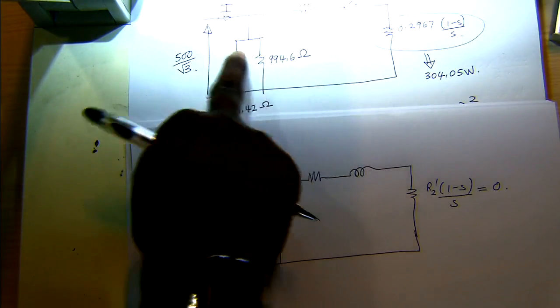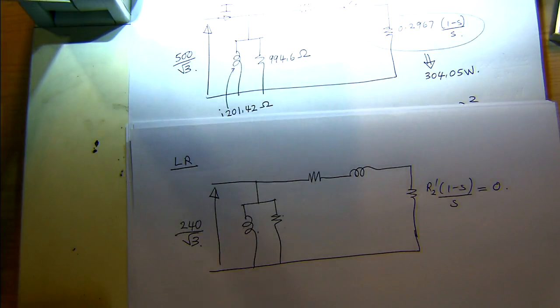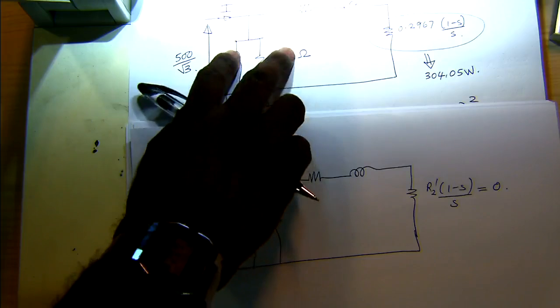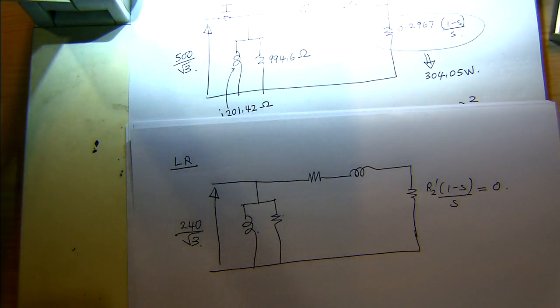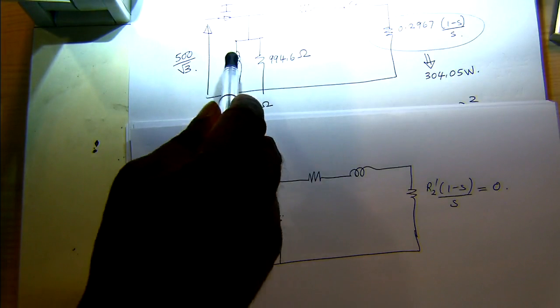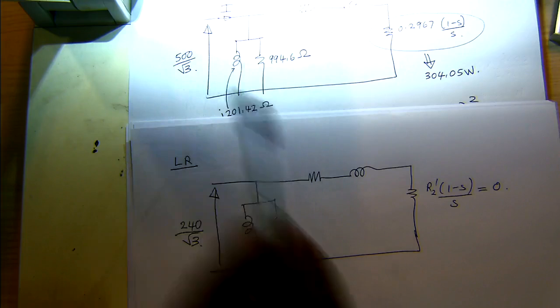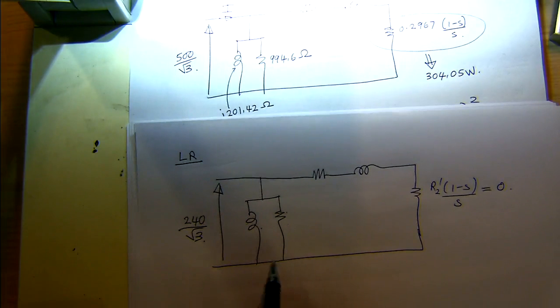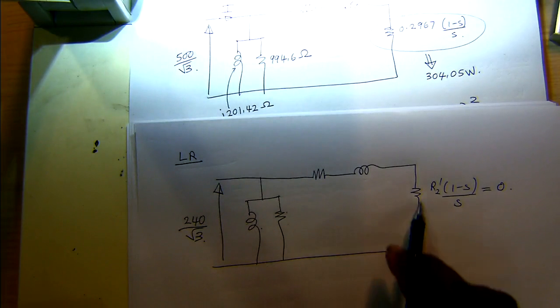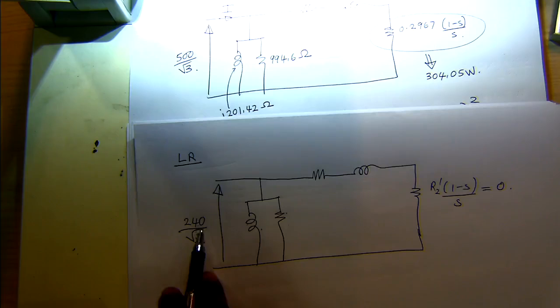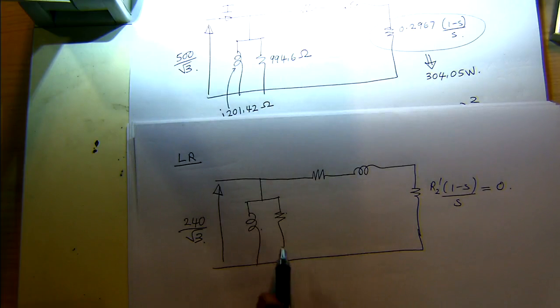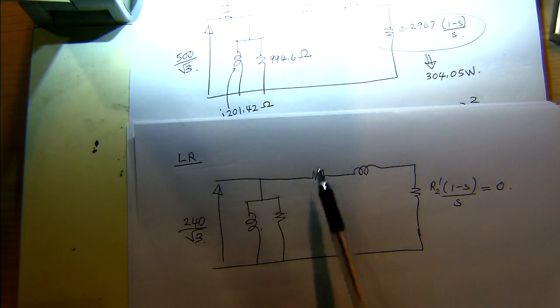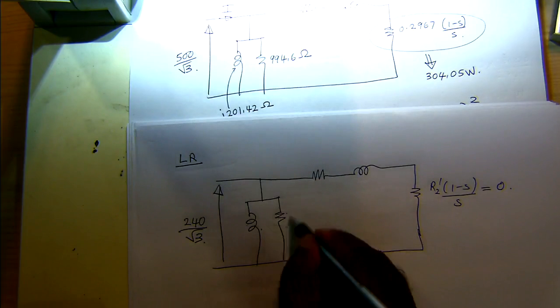You already have these values in your information. You've done the lock rotor test and the short circuit test. So you can see how big a difference it makes if you neglect these or not. Let's say if you were not to neglect it, then you have this, and you are feeding this voltage. You can calculate the total real power, and then you'll need to factor this in as well.